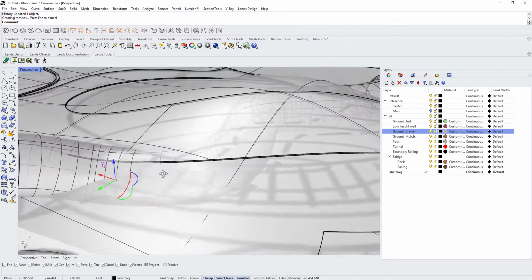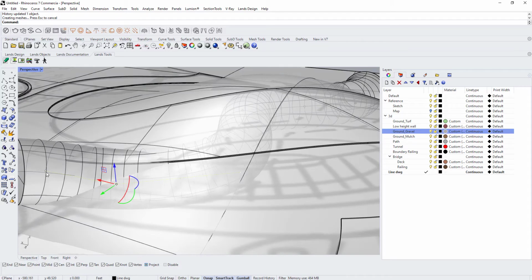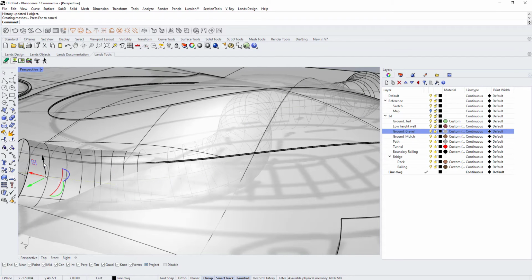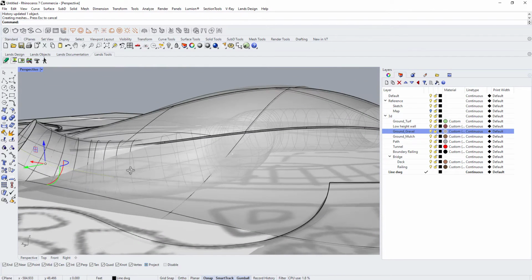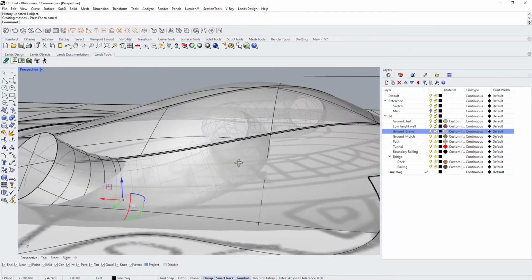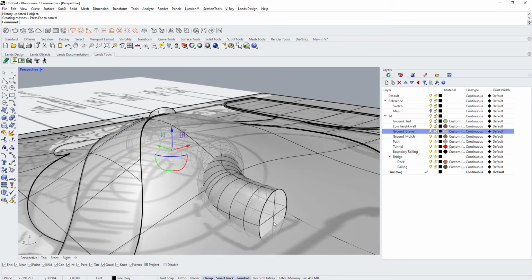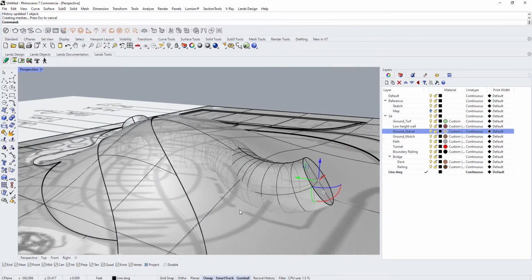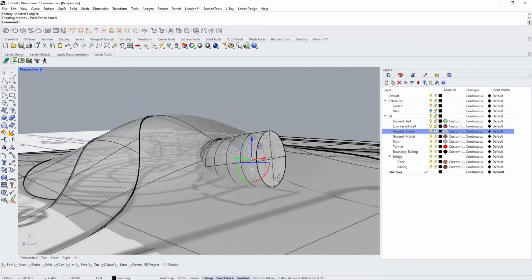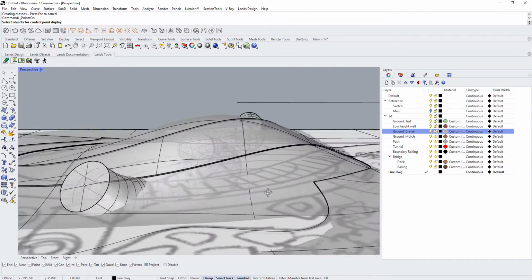That will keep your drawing cleaner. If you move the pipe, it will break the operation of record history, so I would not do that. So yeah, you can make a pipe like this if you want to. Just readjust it a little more, and this is our pipe right there.